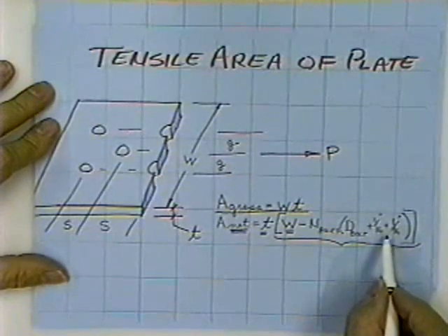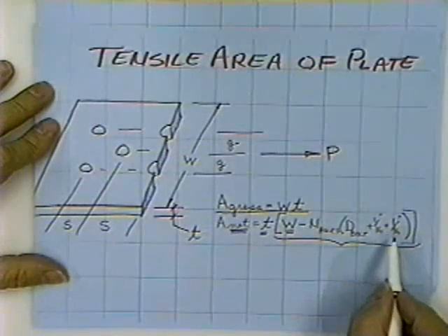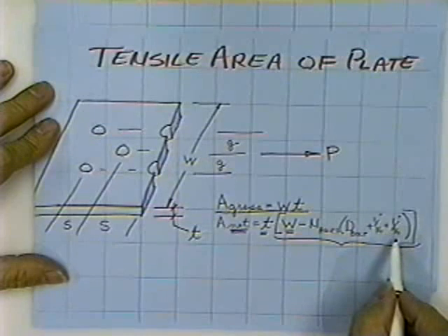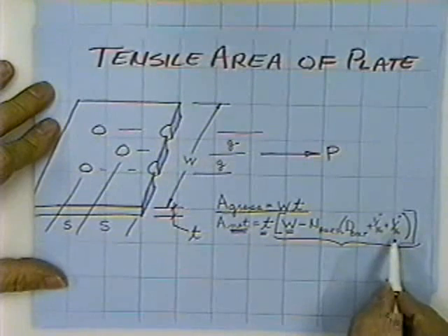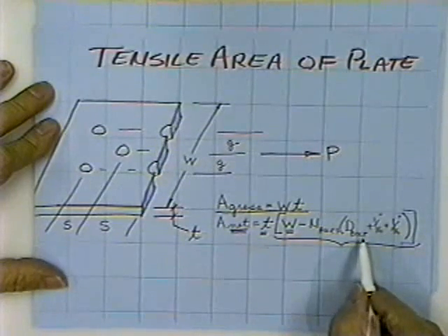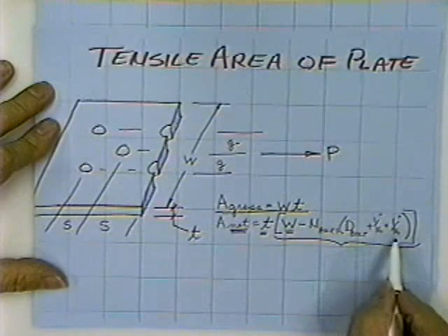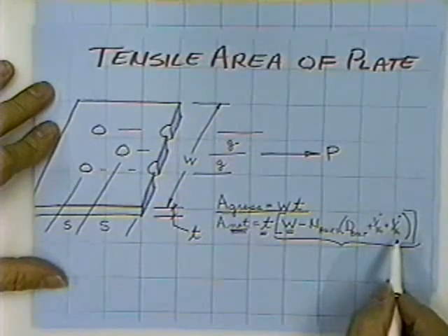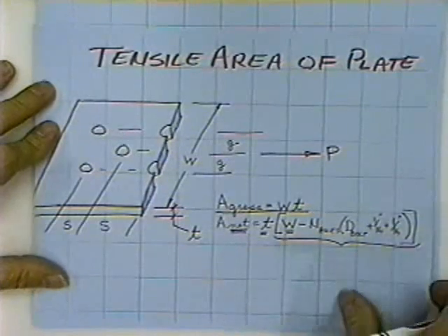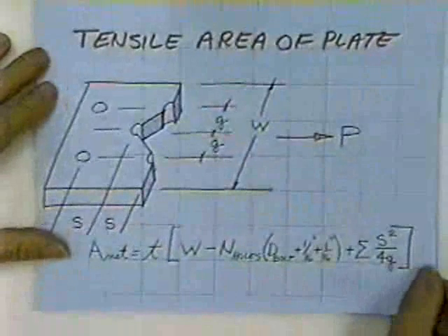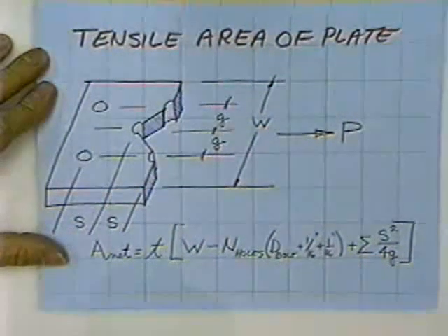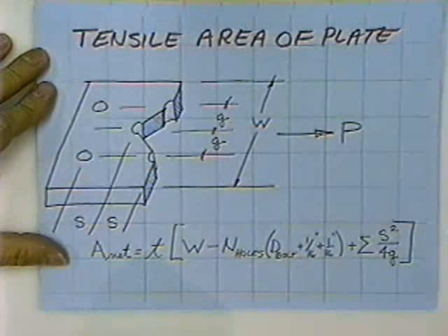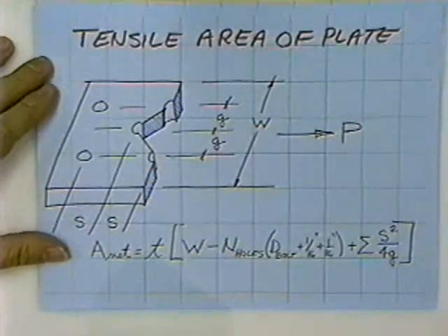And then, because you normally damage the steel to some extent around the hole, they make you add another 1/16 of an inch to the diameter of the bolt. So when the guy says we're going to use a 1-inch bolt, the size of the hole is effectively 1 1/8 inch. Even if that's not the physical size, that's the structural size. Now then, there is a possibility that the plate might find it easier to fail back through that 3rd bolt, and you just have to check both failure patterns.